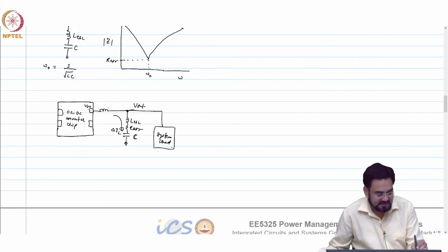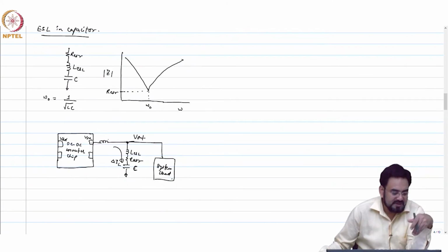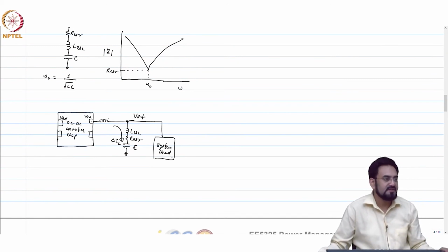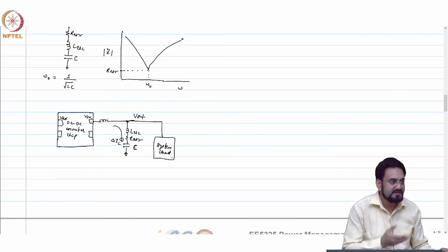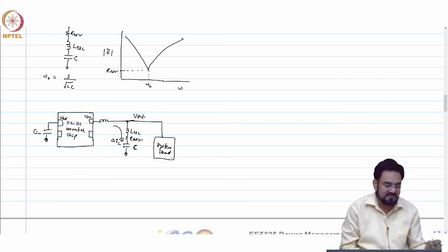And when you are looking at the VDD side, if this is your VDD, you know what the current profile at VDD will be; we have looked at it. That will be like a pulsing current, completely on off. So you need an even more effective cap here, because the ripple current at the output is continuous, but you have more discontinuity on the VDD side, and the switching current flowing into VDD is much larger. It will go from 0 all the way to load plus your ripple at the peak. So in that case you cannot even afford to have a longer trace when you are connecting the capacitor. This we call C-in. You have to put this decoupling cap at the input always. Without this it will not work.